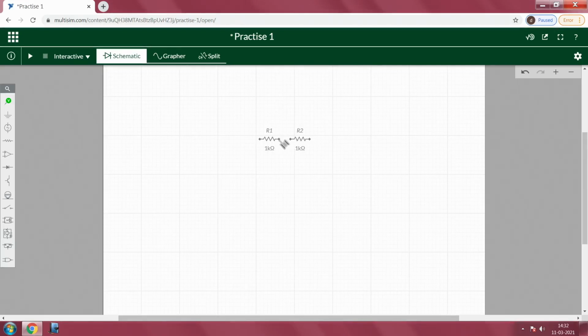So, I will just click here so that I will start wiring. Then wherever it has to be ended, just click at that place, so that a wire will be connected between the two connections. In case you want to delete, just press the delete button. I want to rotate R2 and just drag and place it a little bit down. Now it is a resistive divider.